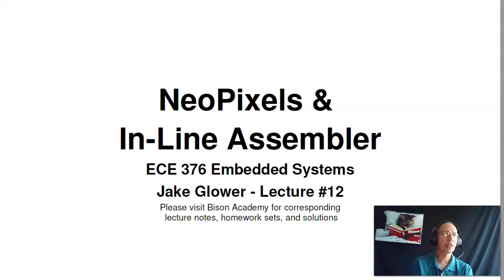In addition, there's inline assembly. The timing is critical on the Neopixels, so I really have to do that in assembly. So I need to mix programs. I'll have a C program at a high level doing stuff, and an assembly program at the low level drive the Neopixel. How do you mix C and assembly together in the same program? That's what we're covering today.